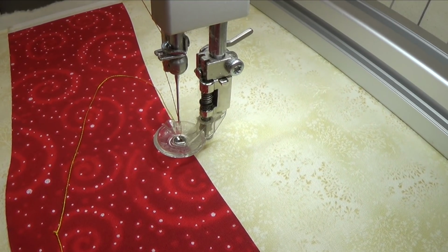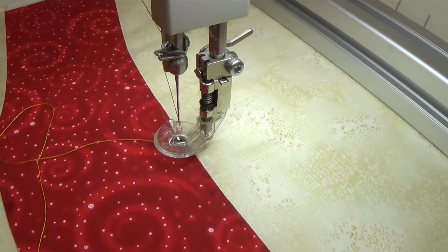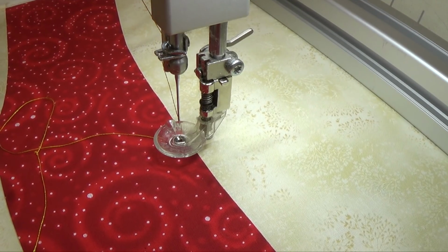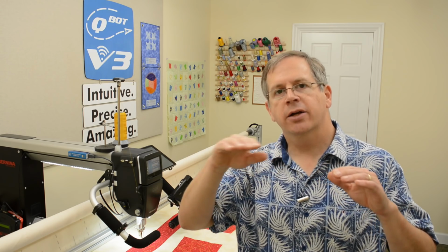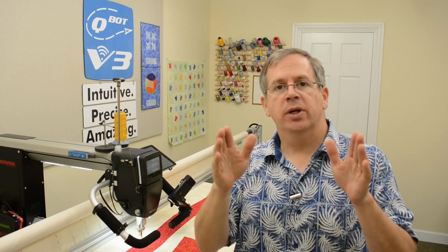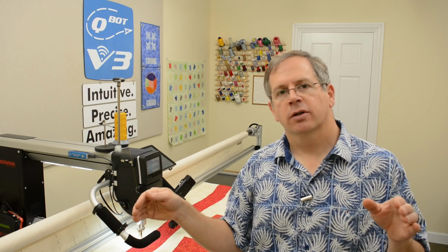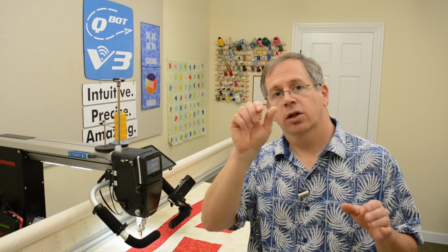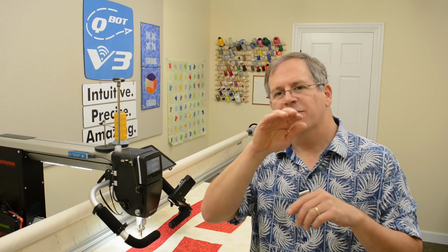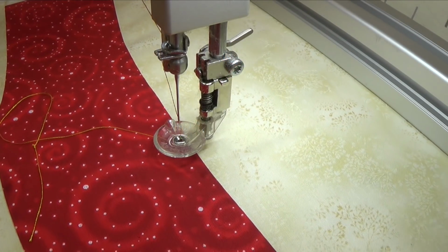And just as a general rule, not to really go off on a tangent here about this feature, but when you're selecting points, if it's a very gradual line or a very gradual curve, you can open up your spacing because you don't need that many points to define that curvature. But if you have a curve that's really sharp, then you do need to have very closely defined points to make sure that you capture the sharper curve. So I'm just going to select points going down the line here.